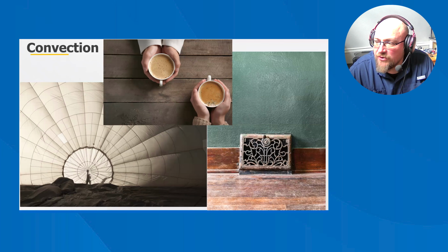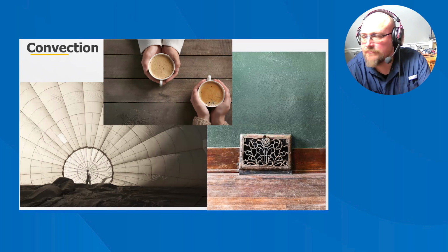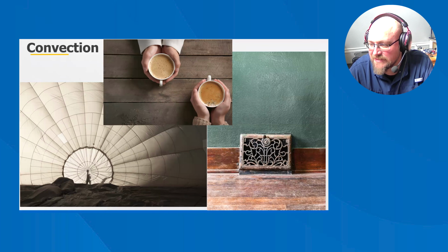Some houses with old gravity heating systems may not have a lot of ducts and pipes, but may rely on large openings in the floors covered with iron grates or grills that allow cool air to fall down through the building. The cool air is allowed to simply fall back to the furnace, hence the name gravity warm air heating system.